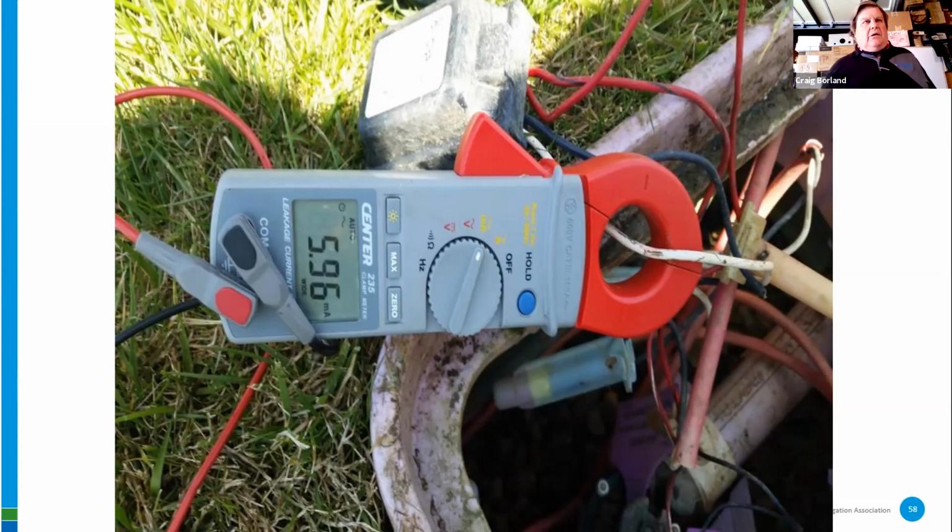When I'm looking for a high current draw on a decoder, this is a bunch of deep knee bends bending over into a valve box, but I'm not cutting any wire. So coming back to fix all that is very simple. I walk my wire path. I'm going to be walking 2,000 steps to find where the bad decoder is. And sure enough, I found the bad decoder, 5.96 milliamps. That's the bad one. You need to replace the decoder. Everything's going to be good and dandy. Fine, works like a champ afterwards.